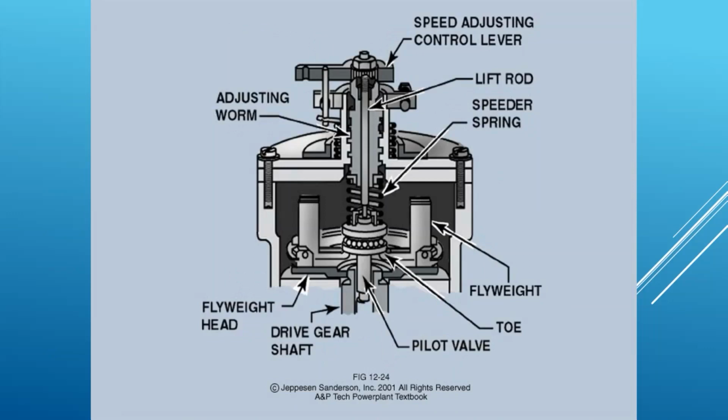To control this, most of these then have this little module on the top, and this is where the propeller lever attaches. And so we can increase or decrease the prop speed by adjusting how much tension or compression is put on the speed spring that counteracts these fly weights wanting to swing out. The fly weights are L-shaped. You can see as the speed increases, they're going to swing out like this, and that causes this toe to push up on this kind of, you'd probably call it a squash plate. They don't have a name for it on here.